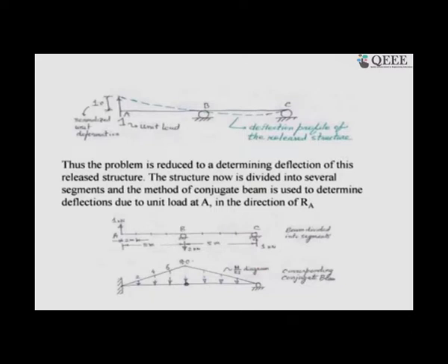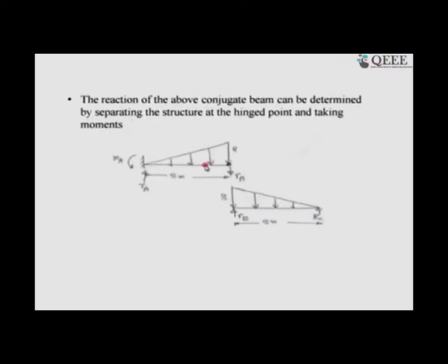My entire work is now to find the shear and bending moment in the conjugate beam, and I will find the slope and deflection. It is the bending moment in the conjugate beam which will give me the deflection. I am after that. This loading is the M by EI diagram of the actual loading. I have now drawn the free body and found the reactions of the conjugate beam, from the M by EI diagram of the real beam, and I am fully ready to determine the bending moment at a section.